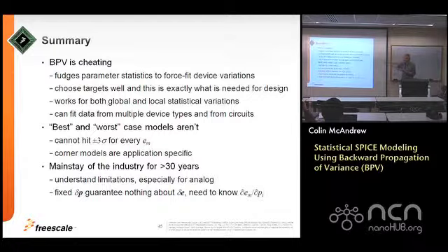And I guess as far as strict statistical variations, I have yet to see something that would cause me to change from this, although people still do continue to look at it. And I think the biggest issues are in the layout dependent effects side. One of the reasons for that is these sort of analyses are generally simulated at the schematic level, often with extracted netlists for parasitics verification. And so the whole paradigm of design has to change there, because by definition you don't know the layout dependent effects until you've got a layout. So you can't do an abstraction in your design at the schematic level if it critically depends on the layout. So I think the layout dependent effects are more significant in terms of needing continued work.